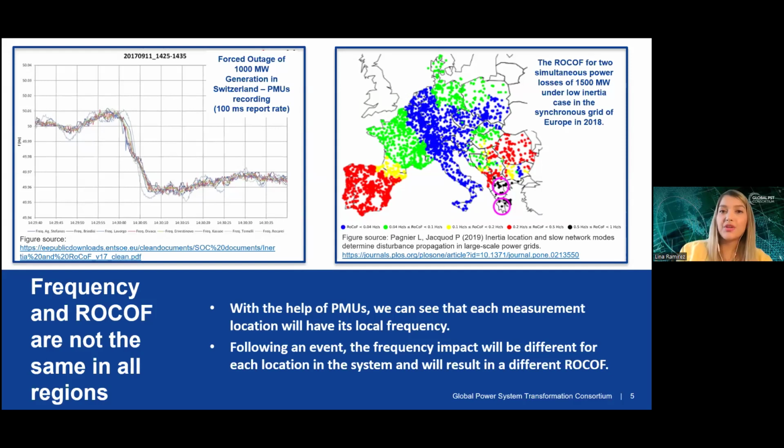So we are considering that this is an issue: frequency is not the same for all the systems, recovery is not the same, and we can start to consider that maybe in some areas, if we are not considering that critical recovery, and we consider only one global recovery, we can start to trip load or generation.